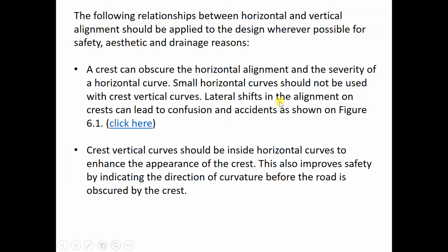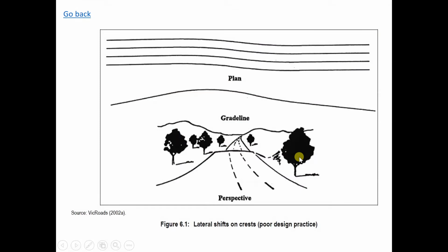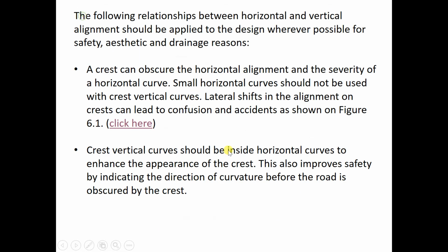Small horizontal curves should not be used with crest vertical curves. Lateral shift in the alignment on a crest can lead to confusion and accidents, which is shown in Figure 6.1. Okay, so lateral shift in the alignment on the crest.